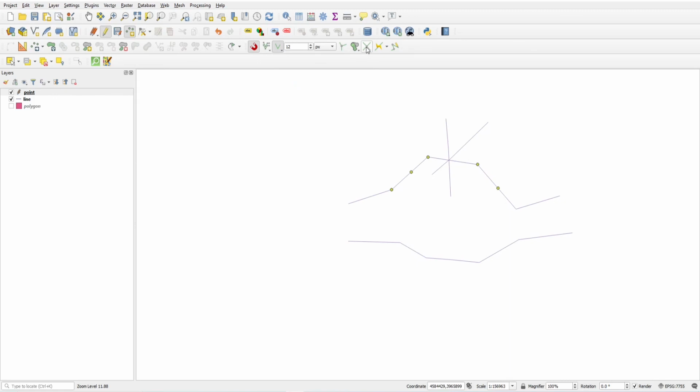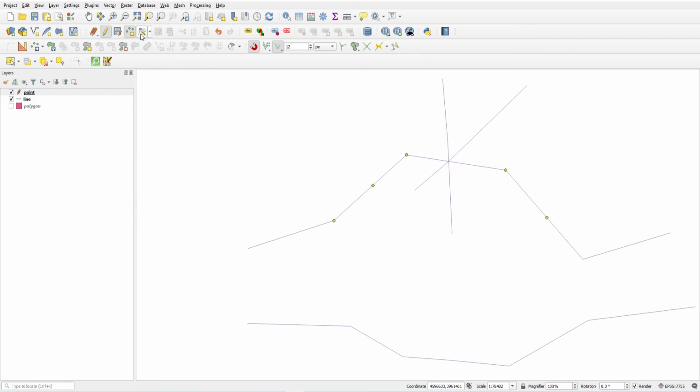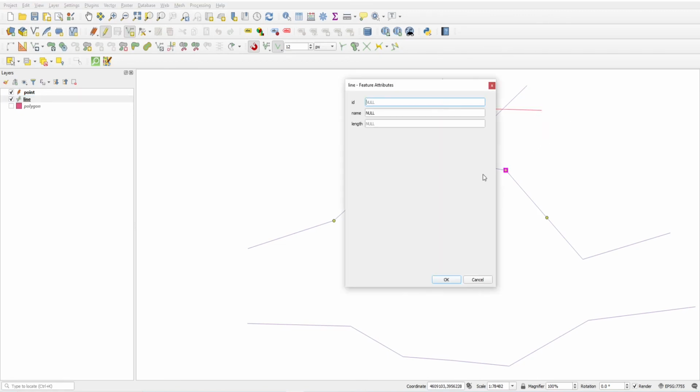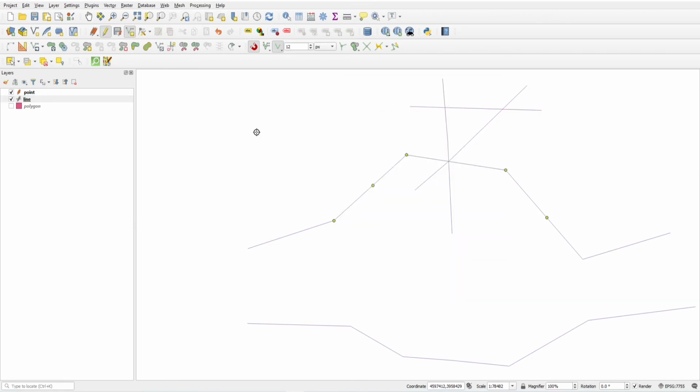And if you want to put it at an intersection, already have a snapping here, just draw a line. I'm just drawing a new line. I just cross these lines. Okay, here this line has only two vertex, one is here and one is here, but I want to put the point feature on these intersections.